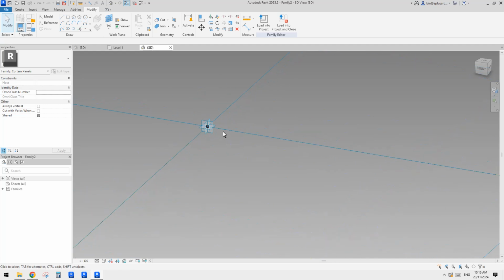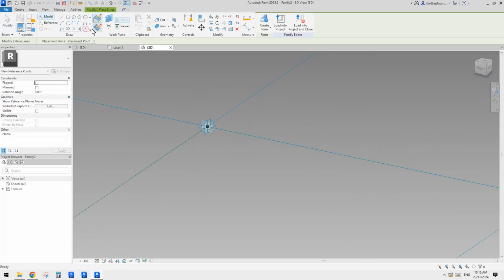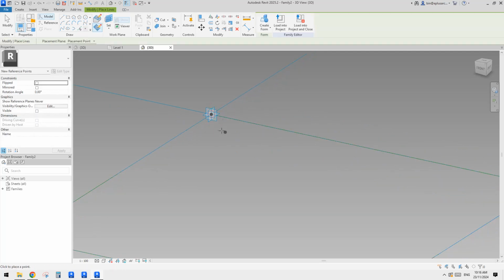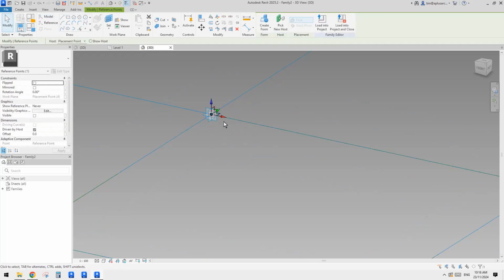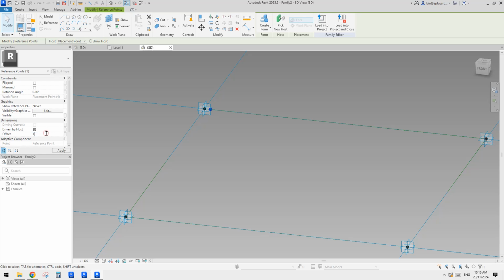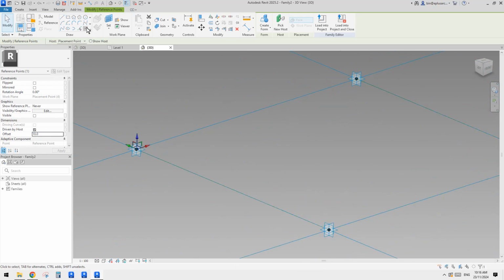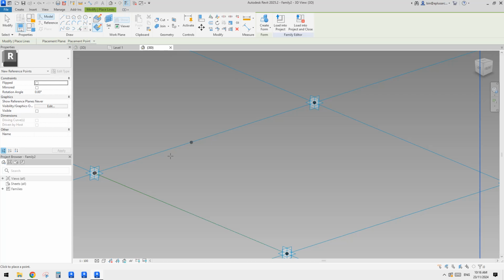Let's do it. So first I create a point. You draw on world plane, set world plane. So I'm going to just use this vertical world plane, and place onto the point, and then select this point. Drag it to the right. Okay, so we can just give it a very small number. For example 10. You can have 1 if you want to, but 10 is easier for us to pick that point.